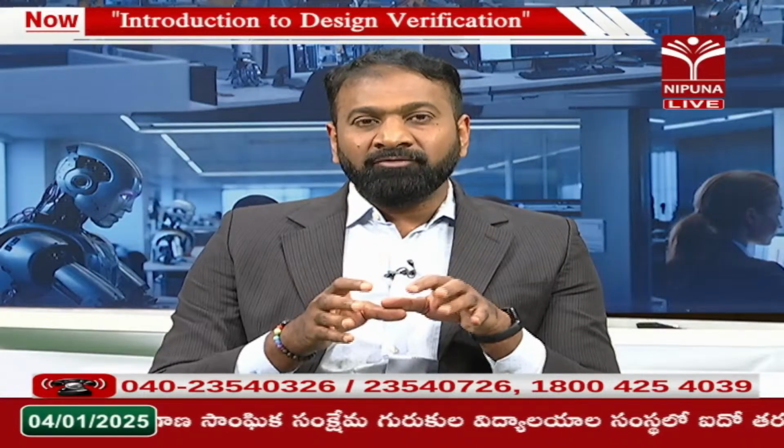But if I have to drive it to the actual design, I will make use of another component called a driver, and this driver will supply these inputs to the design. Generator generates some inputs and passes them on to the driver, and this driver will send those inputs to the device under test. And now, as we said, we have to monitor what kind of inputs were applied, because we have to ensure that our verification goals are met. Are we making progress to meet all the requirements? Are we making progress to ensure the outputs are well verified?